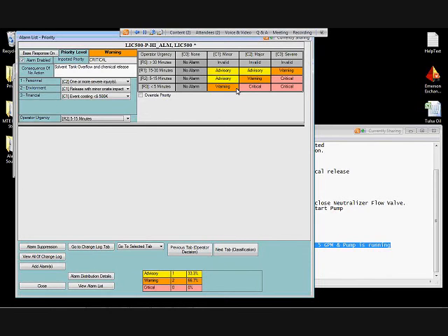We enter that information, and our prioritization matrix says that this alarm should be a warning priority, which is interesting because in the DeltaV system, this is set as critical priority. So Kim's questioning of whether it really should be critical was legitimate based on this analysis that we've done of the consequences, the potential consequences, and the amount of time the operator has to respond. I would say that this alarm should not be critical, but should be warning instead.